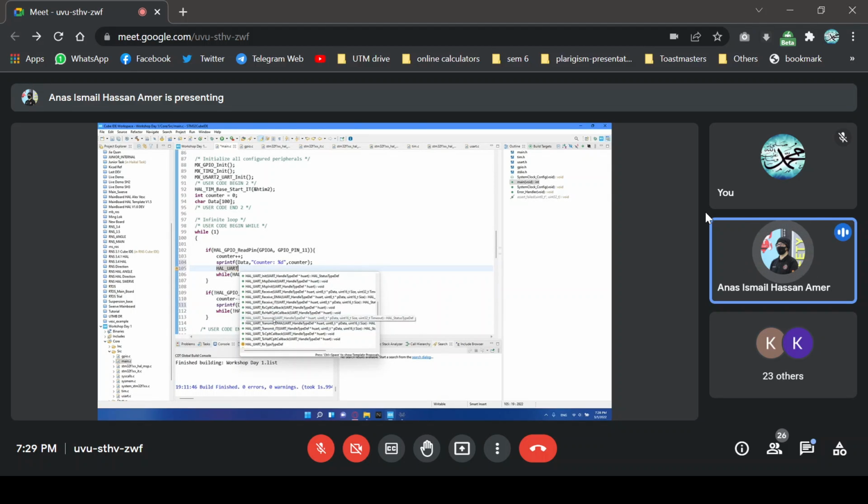Just the normal transmit, which we're going to use. There's DMA transmitting, direct memory access. You can read more on it inside the reference manual. And there's the interrupt transmission, which means begin the sending and then interrupt when it finishes sending. But we're just going to use the normal transmission.